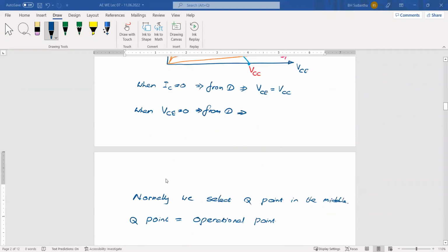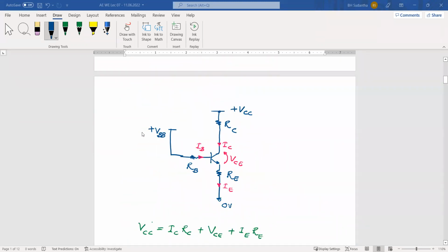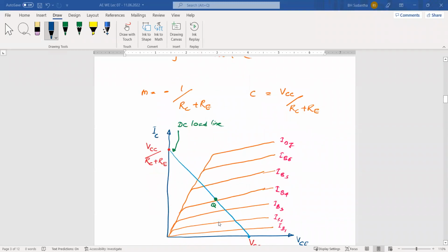The difference between this circuit and this one is that here we have the input voltage. But you know that by providing this VBB voltage here, we have pushed the transistor into this operational mode. Then this is our DC load line. To have this DC load line, we have to provide VBB, the base voltage. Providing this base voltage means we have biased the transistor. We have given certain voltages to the transistor, and we have arranged certain components to receive those voltages at the base terminal and the collector terminal. Having arranged all these things, now we have this DC load line, and we put our transistor operational point in the middle also. To do that, we have to select a particular IB, a particular VBB. Otherwise, we can't place the transistor operational point here.